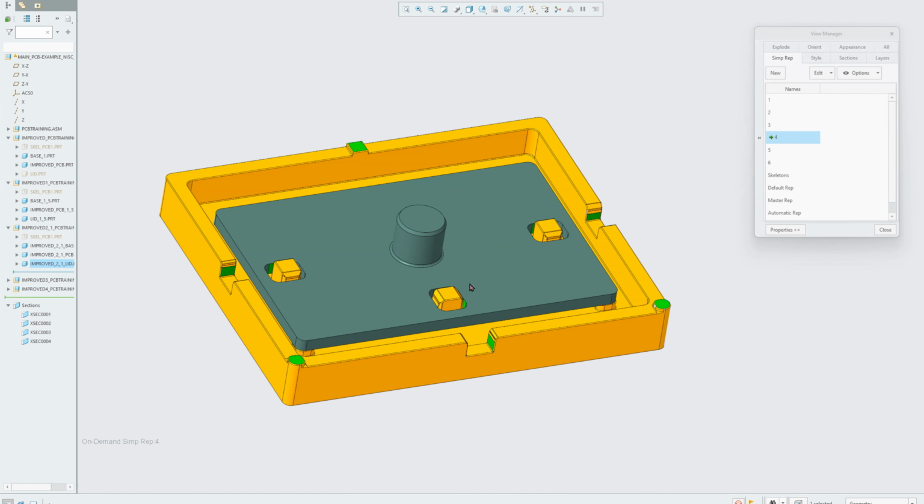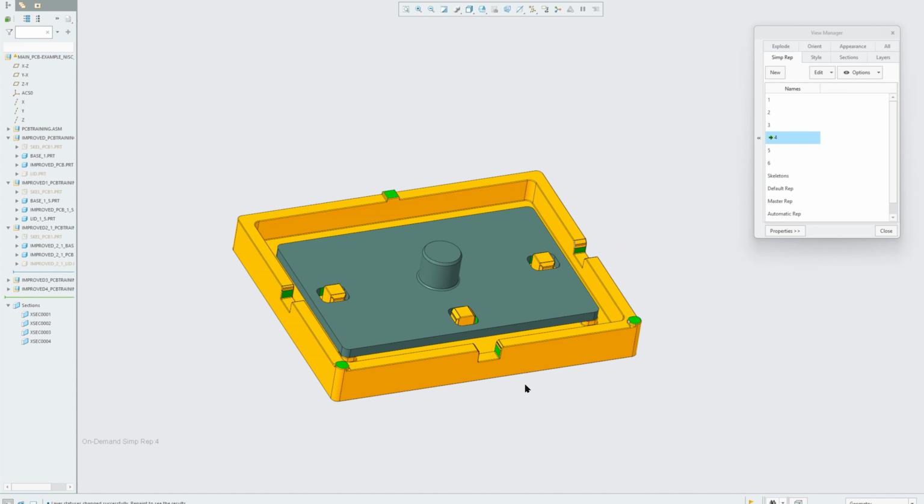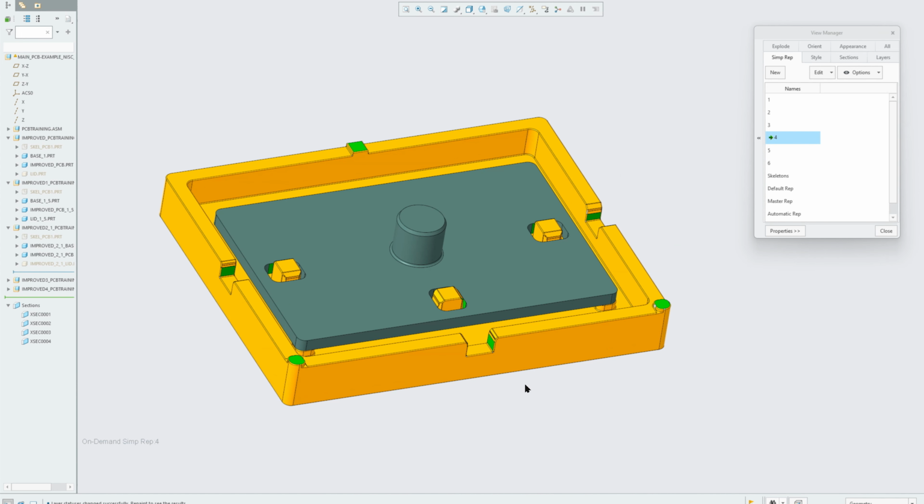And it's the same trick that is applied for the PCB. Before we saw that we actually only had 2 pins, but now we're having 3. And that's a little bit looking back to the first principle. Features that are positioning in the X direction are actually placed as close to the button as possible. Okay, so this makes sense. We localized to get better tolerances without pushing the capability. You have everything centered on one singular reference instead of having offsets. I get that as well, fewer parameters.